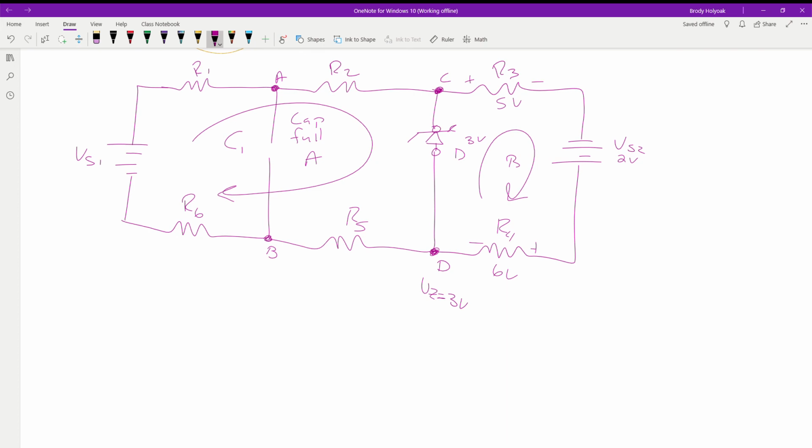Okay? Then at this point, we just start using nodal analysis. Because we're going to get a current coming here, current coming here, current going this way, current going around, and we'll have some current flow in one of these 2 directions. Then once we have that, we can figure out the current that's going through here, the current going through here, we have resistance, we can solve for voltage. Same with these guys, currents, voltages. And then, once we have our diode back in there with its drop, we can solve for the value of our capacitor just by using Kirchhoff's voltage law. We're going from here, walking around, to here.